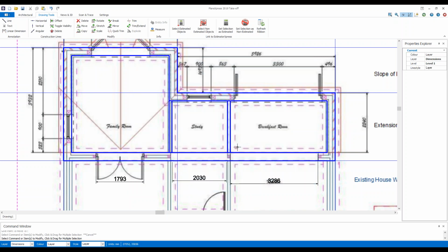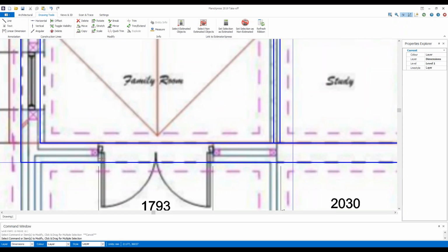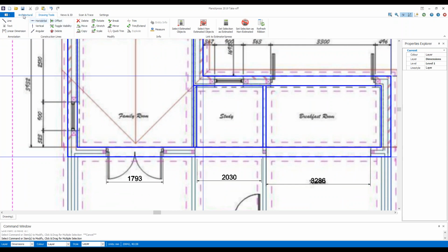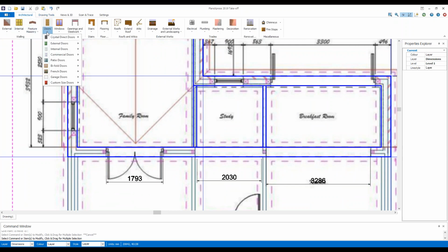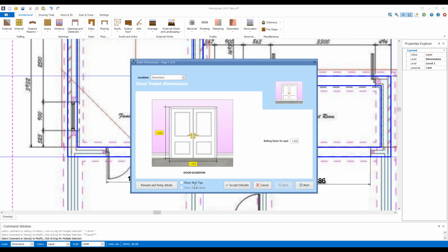Awesome. Okay, so the openings that we're going to be putting in are a bay window, 2 smaller windows, 900mm each, bifold doors, structural openings, and a double door coming out here with reveals slightly deeper, I believe. I'll figure that out in a second. In fact, you know what? I'm going to figure that out now. So let's just go onto the doors drop down here. And I'm going to use internal double panel doors. And I will use the top one just there, because that'll make it 1800.